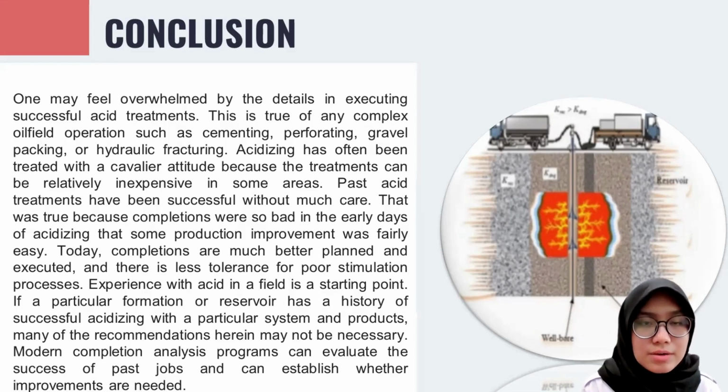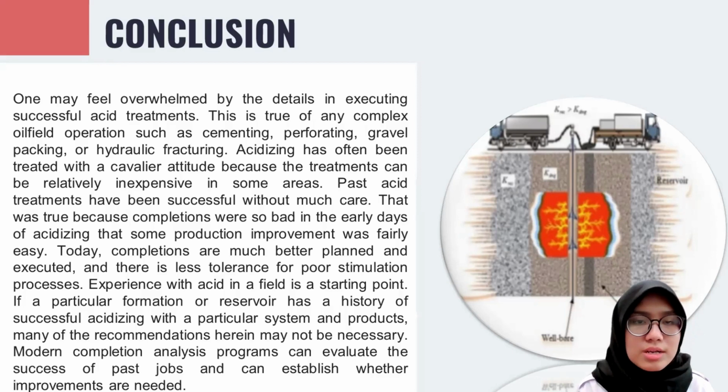Experience with acid in a field is a starting point. If a particular formation or reservoir has a history of successful acidizing with a particular system and products, many of the recommendations herein may not be necessary. Modern completion analysis programs can evaluate the success of past jobs and can establish whether improvements are needed.